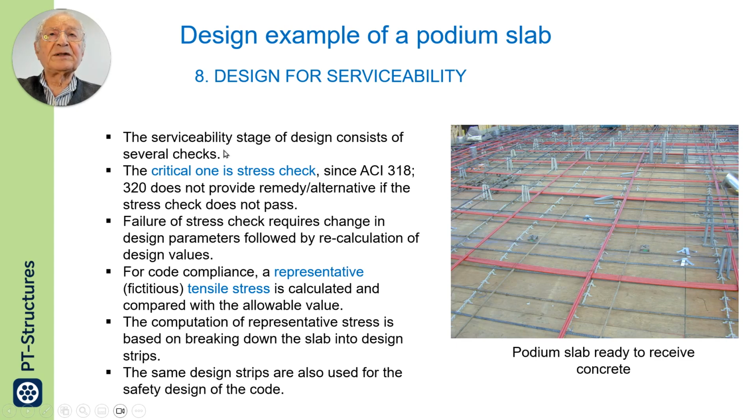The serviceability stage of design consists of several checks. After I put the tendons and obtain a solution, I go to serviceability check, and then I go to safety check, and then I go to initial condition check, followed up by detailing. So the critical one is stress check.